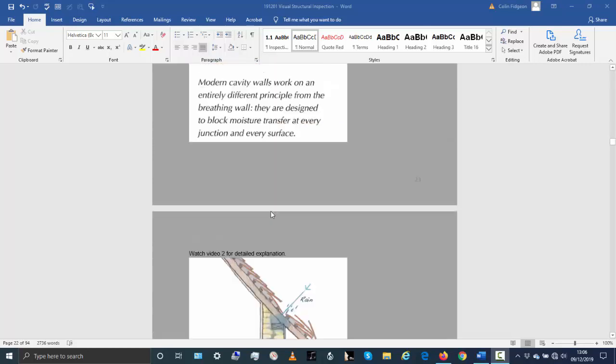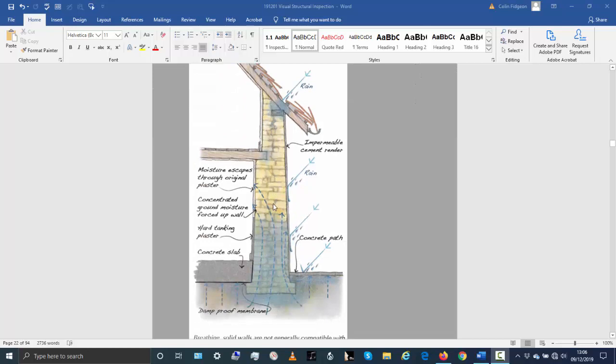However, what happens is you can have old stone buildings that were designed to breathe and let rising damp evaporate not work the way they were supposed to work, because people often put on a cement render externally.